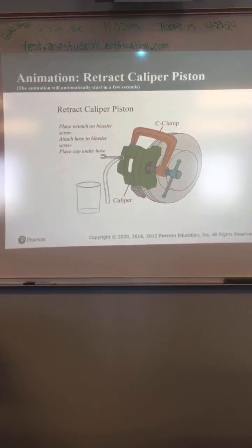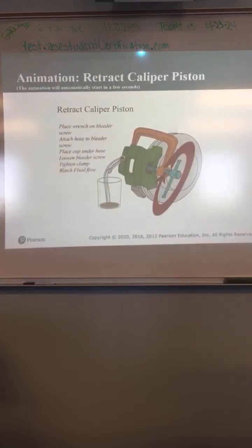Sometimes people do this, you can, or you can't, it's up to you. What they're doing here is replacing the brake pads, and you have to compress the caliper piston back into the caliper. Sometimes people open the bleeder screw. So what happens is you're actually purging the fluid out of there instead of pushing it back through the system. Really, it doesn't matter either way. If the brake fluid looks bad and you're gonna do a flush anyway, it's a good idea to do that. That way you're pushing that old fluid out of the caliper.